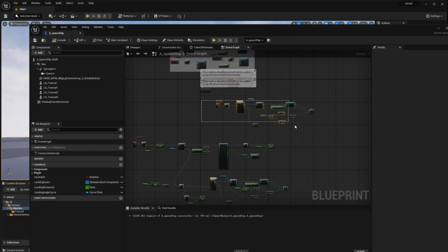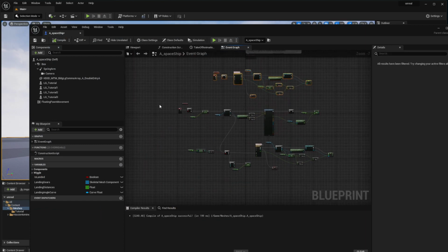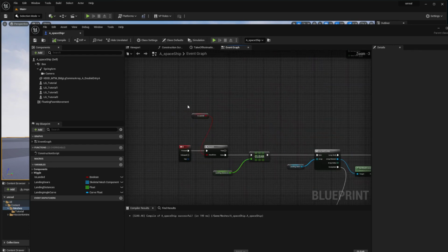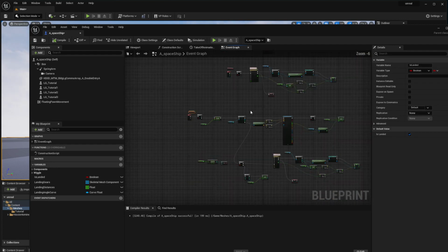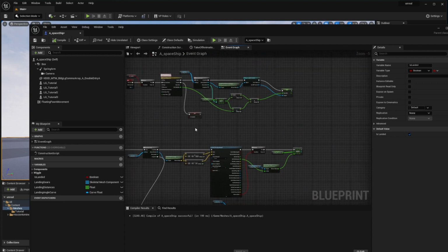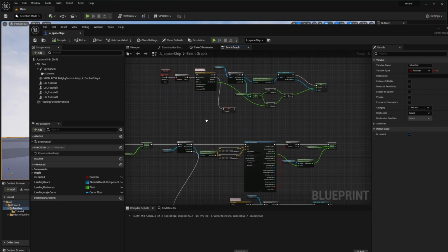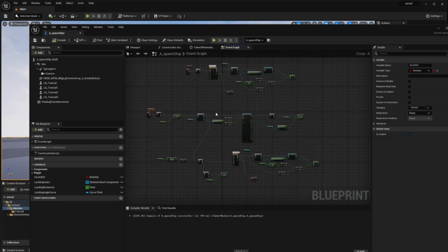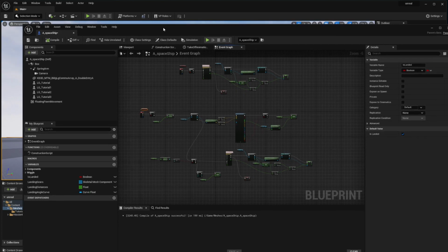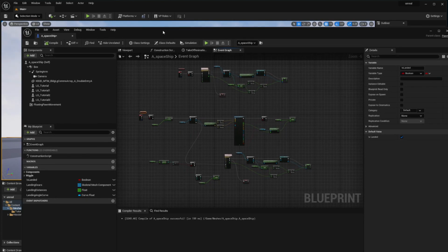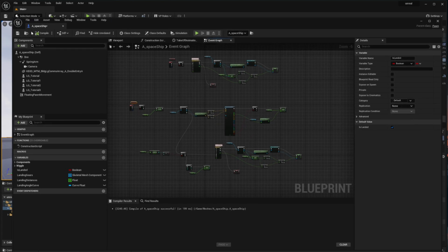This is the setup that I had in the beginning of the tutorial. Hope that this helps the viewer that requested this tutorial, and it will help you to use any morph target animations in your characters. It doesn't really only need to be for this type of animations. Morph targets are often used for facial animations and for other organic characters. It's really beneficial to know how to use morph target animations, and this way with the post-process blueprint is the easiest way, I believe, that you can use to apply these animations to your blueprints.